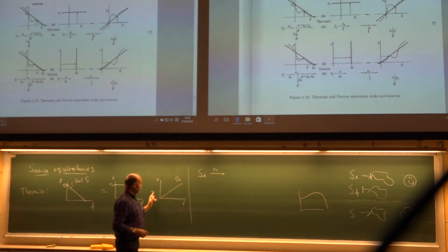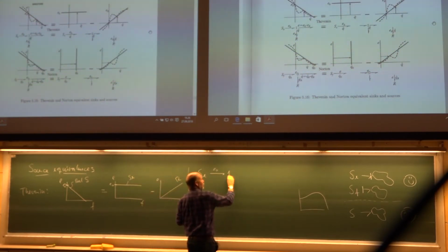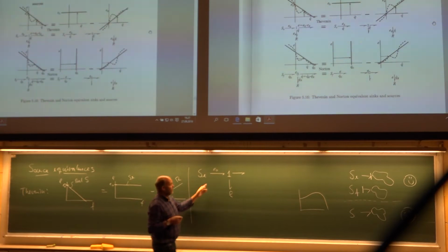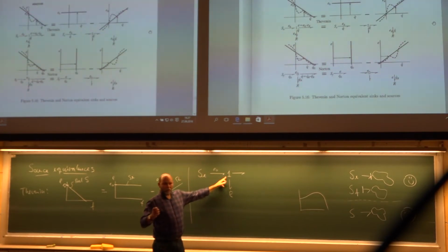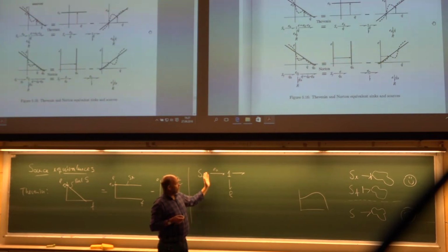Then I will have a subtraction. Then I will use a one junction down here to this resistance, and then I continue. Well, a one junction, that's common flow, but I have to take the summation rule for the efforts. The efforts should sum to 0 here. So what comes in equals what goes out.